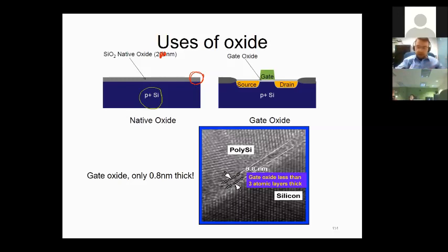As for the other types of the oxide, we've talked a lot about MOSFETs, right? We said that they were our switches, so we could conduct or not conduct based on the third electrode that we had on the gate. So with respect to the voltages, we were enabling the conduction or not. In this case, this transistor as the fundamental block of all of our computation and all the science today, we need to have super good high quality gate oxides just underneath the gate.